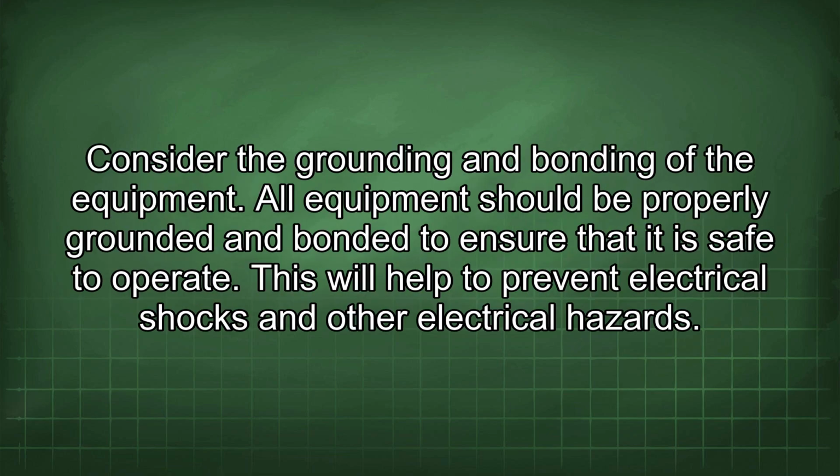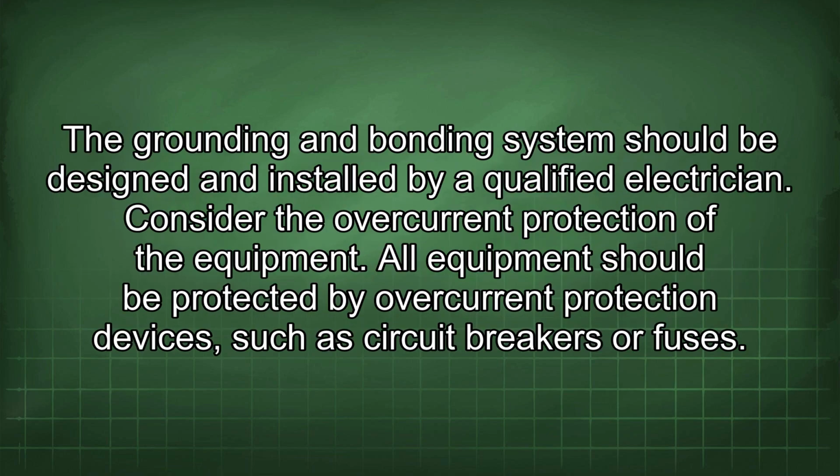Consider the grounding and bonding of the equipment. All equipment should be properly grounded and bonded to ensure that it is safe to operate. This will help to prevent electrical shocks and other electrical hazards. The grounding and bonding system should be designed and installed by a qualified electrician.